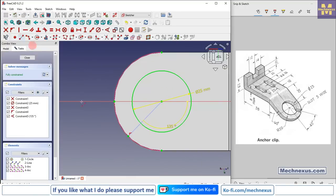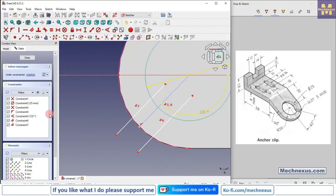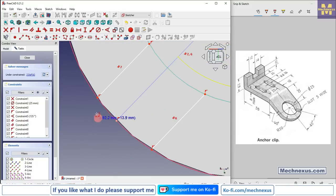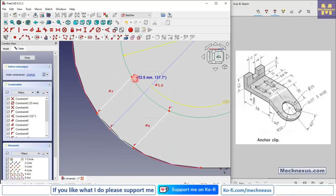so then this face will be normal. And now we will draw the two lines, which will be parallel to this construction line. Make it parallel. Select this and this and make it parallel, and here we will use the trim tool to remove the unnecessary geometry, and we will use the 3-point arc. Create an arc.